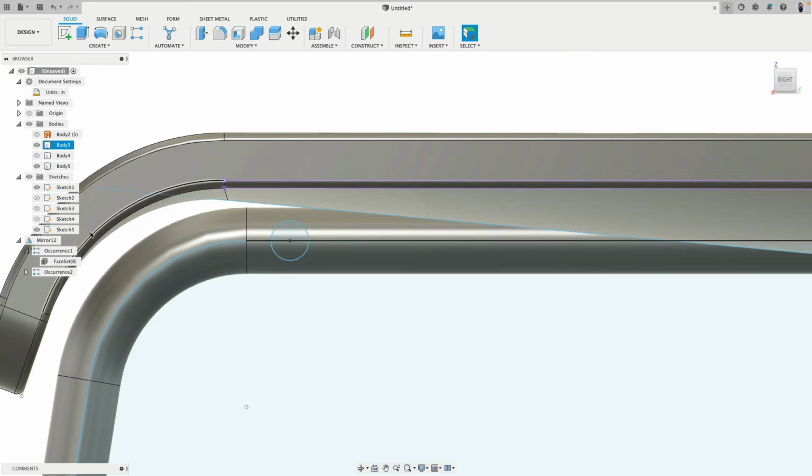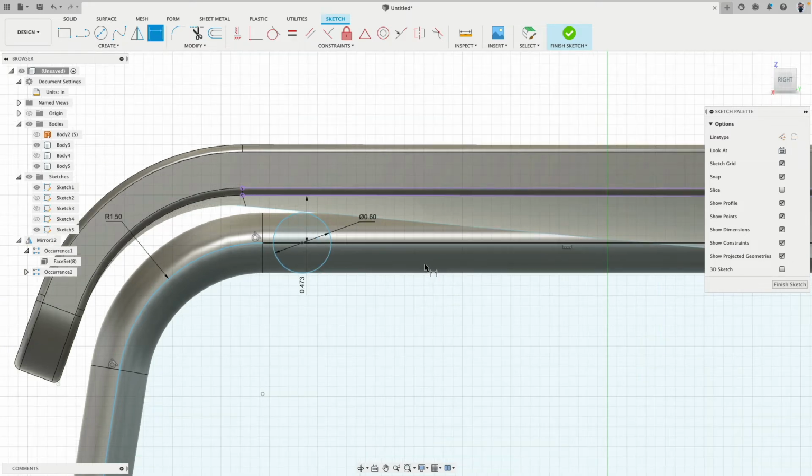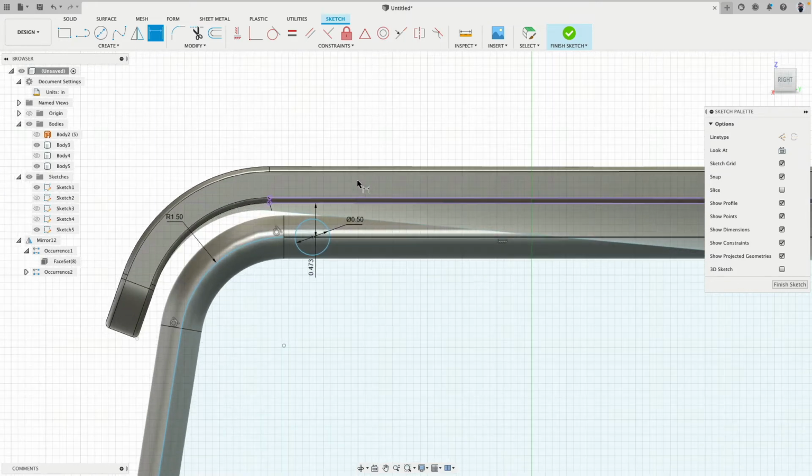So now go back to this one. Oh, and actually that's a diameter. Yeah, I was confused for a second. So we can do the same pipe. It will be a little bit more of a trick to perfectly grind everything and weld it together. What we can do is we simply make this pipe a little bit smaller. So I can drill a hole in the bigger pipe and put the smaller pipe in. It's kind of like a pilot hole, and then we weld this all together.